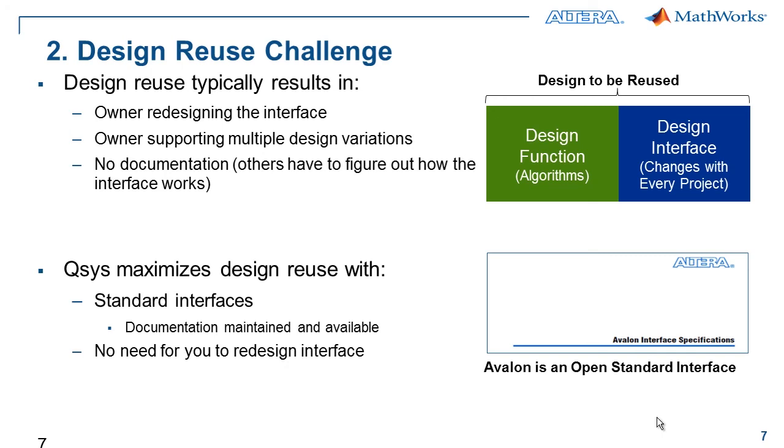Qsys maximizes design reuse by using standard interfaces. For example, using the Avalon interface makes it easier to integrate because the Avalon interface is a standard interface well understood by Qsys, publicly documented and maintained. Standardizing on an interface eliminates the need to change the design for each project, thus making the design easier to be reused.